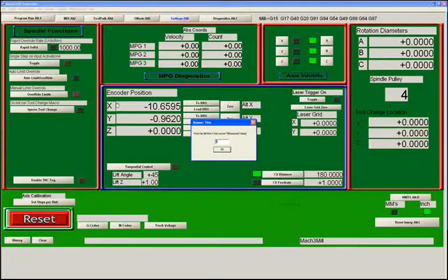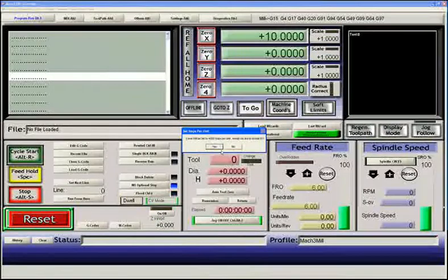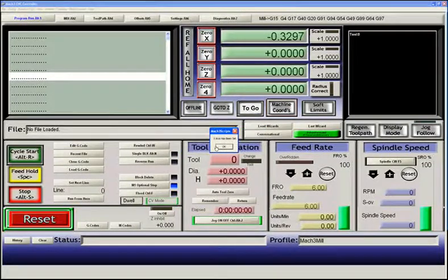When we do that, the system actually moves. If we now measure the system, your axis would have just moved from its position to a new position. You have to measure that movement. If we tell it that we actually moved 5 millimeters, it will now set the axis to 4,000 steps per unit, which will be accurate. We say yes, and the x-axis has now been calibrated.